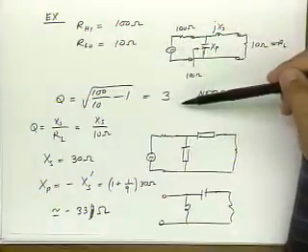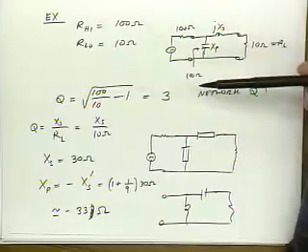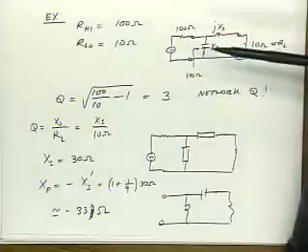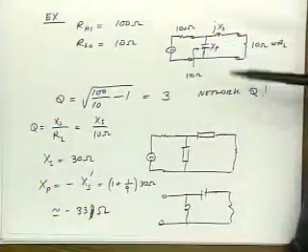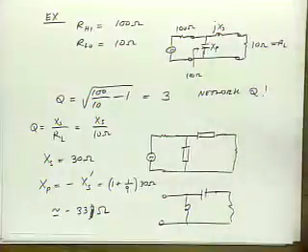Then our Q factor would be much larger, and the circuit would be much more narrow band. So the higher the transformation ratio, the more narrow band the solution ends up. And that's a problem. In many cases we want to be able to control the bandwidth, either to make it more narrow band or less narrow band, as we'll see. We'll come back to that issue later in the lecture.